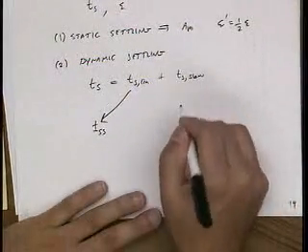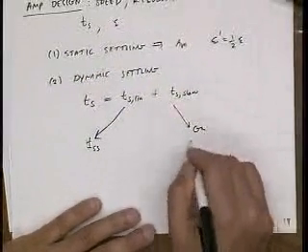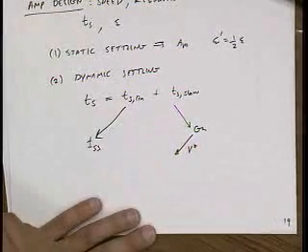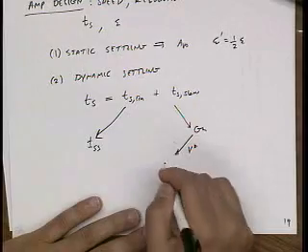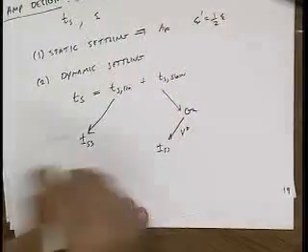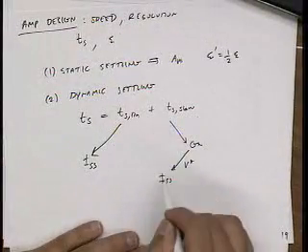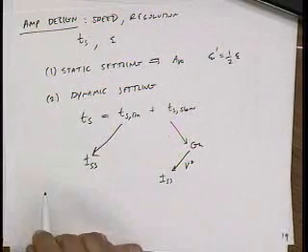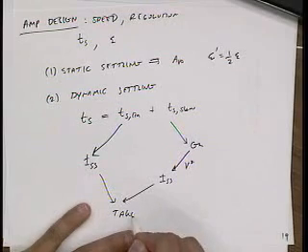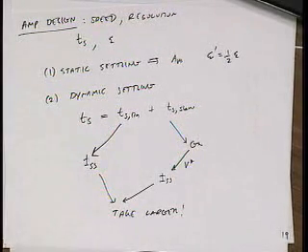The nonlinear settling time, on the other hand, is a function of gm of the device, right? And if you fix your V star, then it just becomes also a function of current. So at some point, in order to improve the settling time, also in the nonlinear region, you have to, again, change the current. So at the end of the day, it's the larger of these two that determines the power consumption that you need in a circuit.